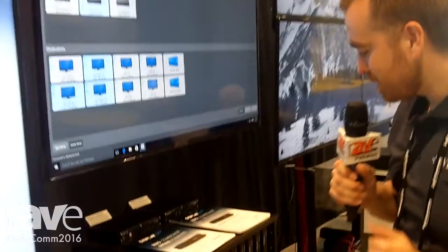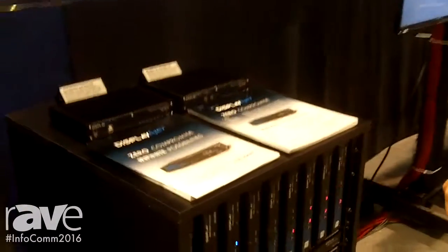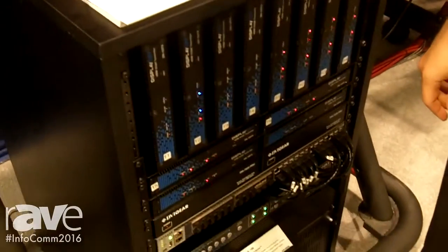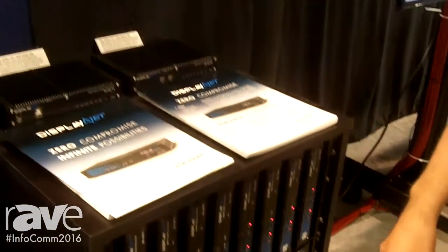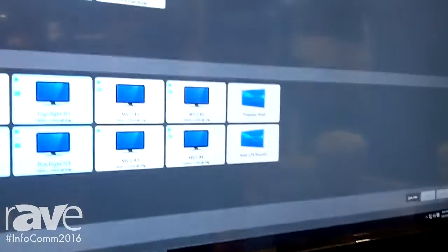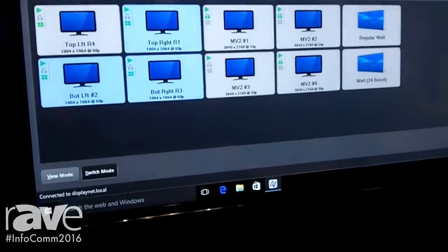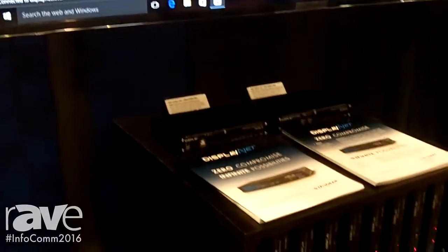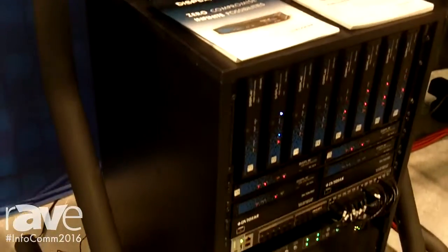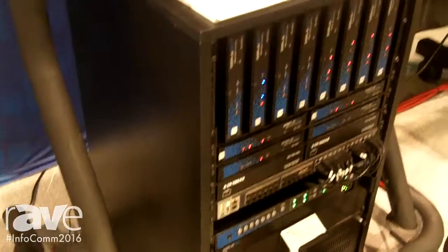So a few points on this. The DN-100 series supports HDMI, RS-232, bidirectional IR, 1 gigabit Ethernet, all over a 10 gig Ethernet link using Category 6A copper cable. Now, from the transmitter to the network switch, we can go up to 100 meters or 330 feet. From the network switch to the receiver, we can go another 100 meters or 330 feet.